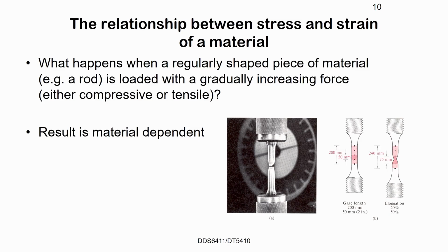Under plastic deformation, the amount of material is conserved, or the volume is conserved. So if you extend something plastically, you're going to have to reduce the dimensions transversely in order to have the same amount of material. Otherwise, you would be creating free material. We all want to do that without any cost, but in reality, things will reduce in dimension in the transverse direction.